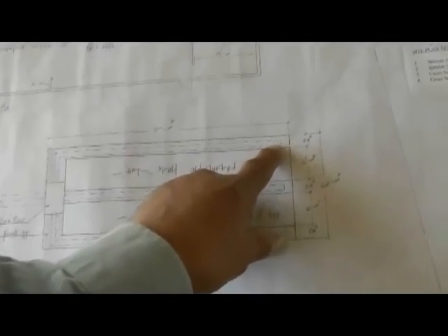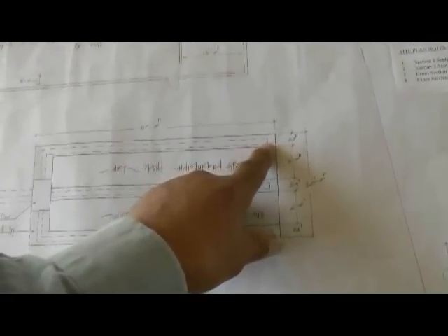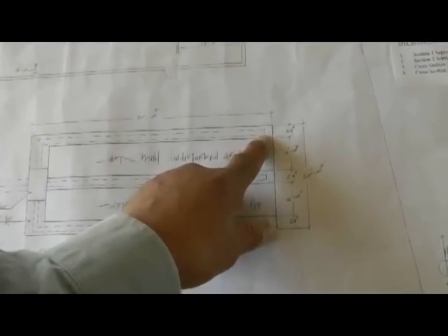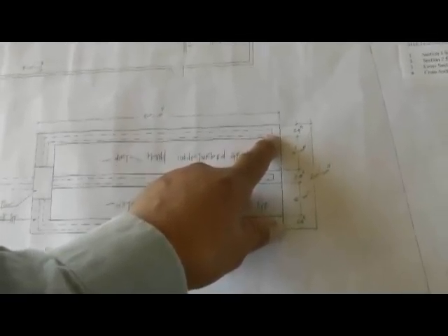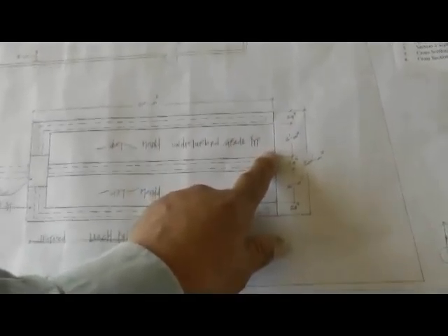There's 3 of them in between. Here are your measurements. You'll see those on the plan that you have, that Mike has. It shows that each leach dig out is 24 inches wide, and then it goes to 6 feet wide between each leach dig out. Okay? You'll see that on the plan you got.